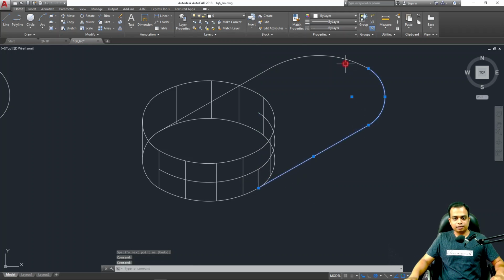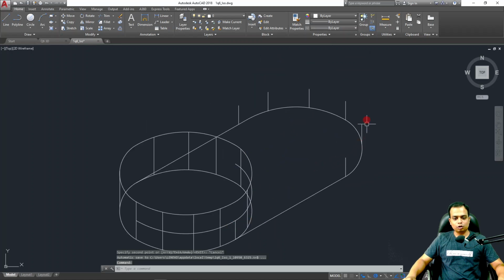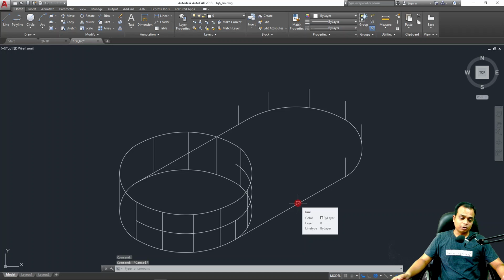Okay. Select. I can do the selection process. If you're doing it on AutoCAD, follow my steps. If you're not on AutoCAD, what you can do is keep on making points here, I mean, at regular intervals, approximately. And then join all of these points in proper sequence. You are going to have the same profile lifted by a height of 15. Okay. This is how you do it.